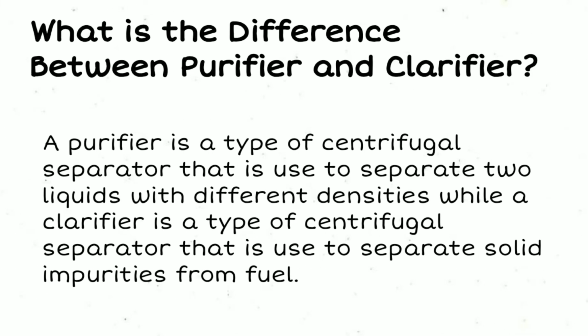What is the difference between purifier and clarifier? A purifier is a type of centrifugal separator that is used to separate 2 liquids with different densities, while a clarifier is a type of centrifugal separator that is used to separate solid impurities from fuel.